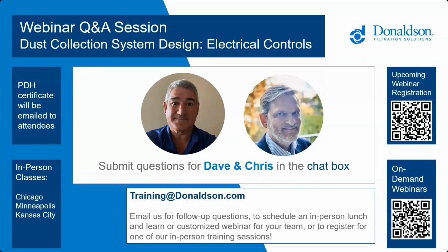All right, thanks, guys. Next question. Does the exhaust fan for weld fume need to be rated for high temperature, like greater than 500 degrees Fahrenheit? I have not seen a weld process that has been elevated to that temperature that I've operated with, even plasma cutting tables, laser cutting tables, manual welding, all that stuff. I can't see it getting above ambient, which might get to 100, 125 or possibly 150, but I don't see it getting up more than that.